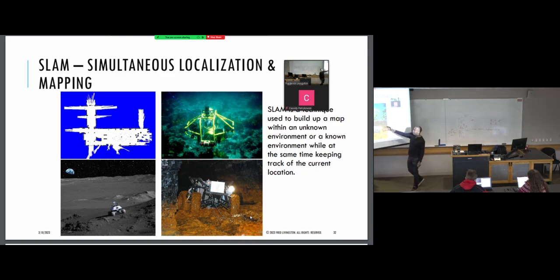And it can be done in space, underwater. You can't use LiDAR underwater, but you can use some other kind of system, like sonar or acoustic sensors. Doing the same thing, you need some kind of laser scan or rangefinder, and you need your IMU. Those are the only two sensors you really need. You need to know the velocity to get your position back, and you could use this algorithm. Those two sensors are available underwater, on the ground, and even in space. We have sensors equivalent to that there.